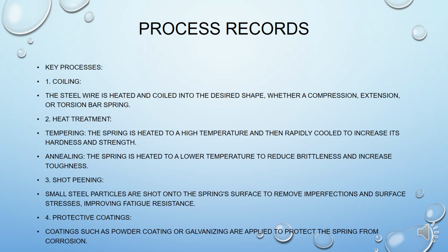Quenching. The spring is heated to high temperatures and then rapidly cooled to increase its hardness and strength. Tempering. The spring is heated to a lower temperature to reduce brittleness and increase toughness.